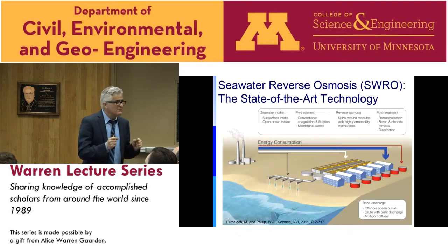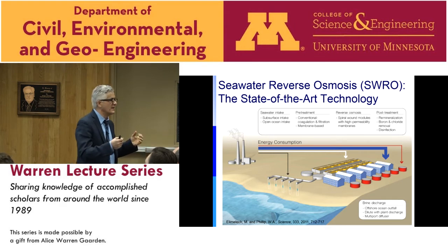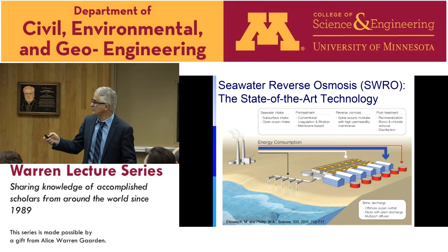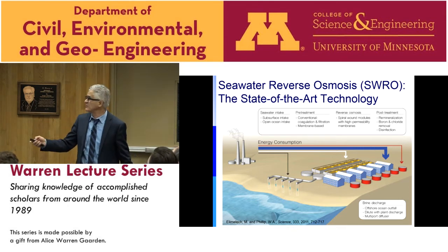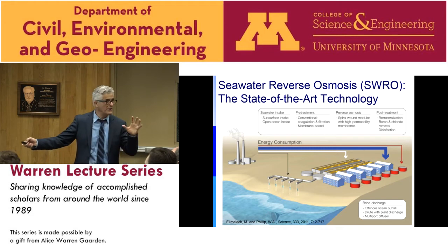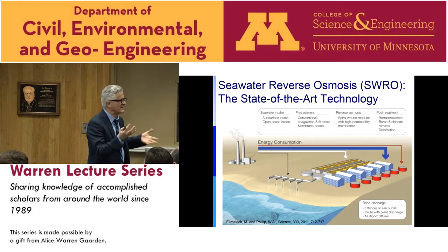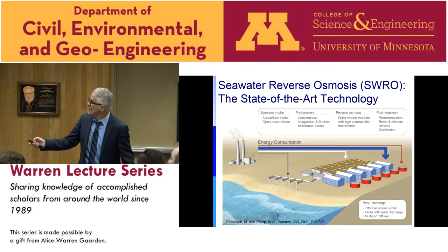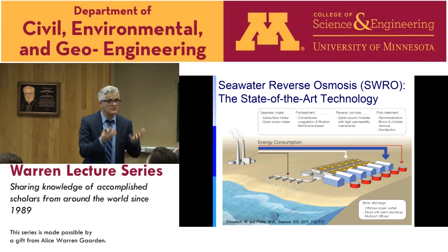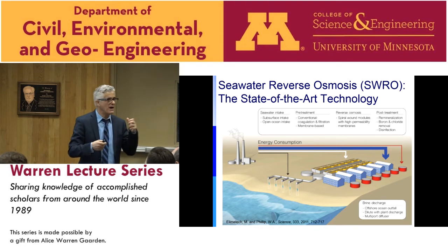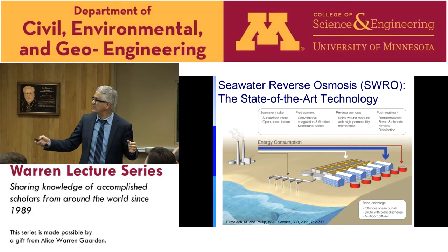So the key process for seawater desalination is reverse osmosis technology. Although there are some other older technologies in the Gulf countries that involve thermal desalination, they are very energy intensive. So the state of the art is reverse osmosis technology. For those of you who never heard about reverse osmosis, I would like to guide you. You have an intake of water from the ocean. You have a pre-treatment stage similar to the way we treat water for drinking water supply, more physical and chemical processes. We have the reverse osmosis stage that does the actual desalination. And then we have a post-treatment to add minerals and sometimes to remove some other things that are not removed by reverse osmosis.